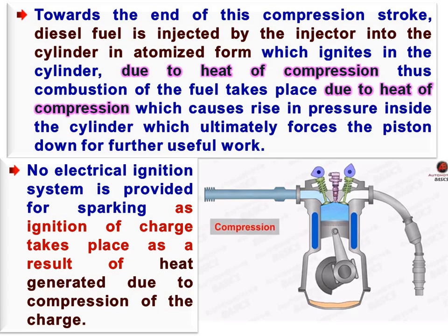air inside the cylinder during the compression stroke, the pressure upon the air becomes very high, and there will also be a high temperature of these gases. According to the ideal gas equation, PV = nRT. So this heat of compression ignites the fuel as it is injected at the end of the compression stroke through this atomizer, or we can say injectors.